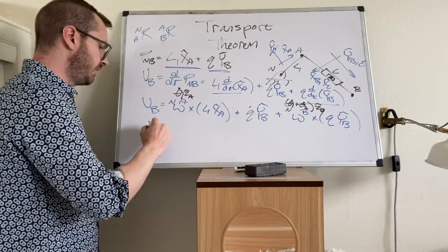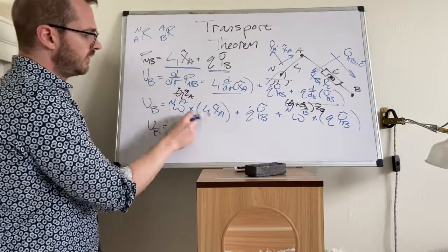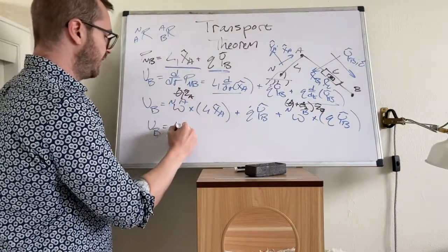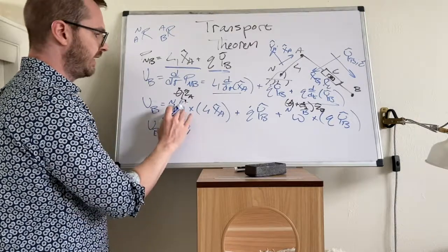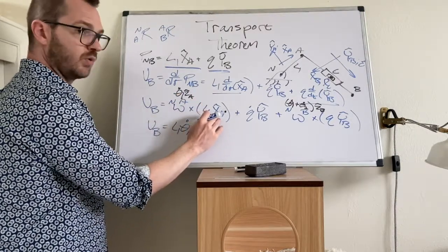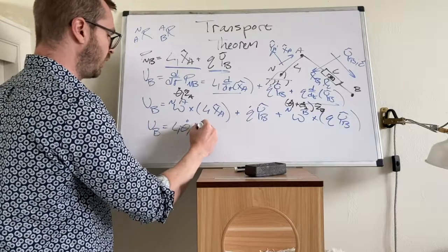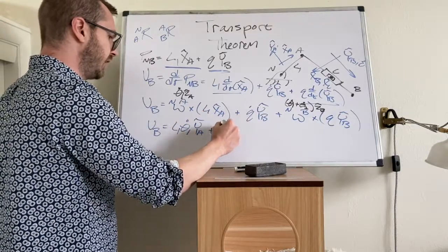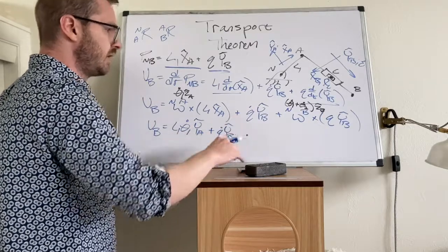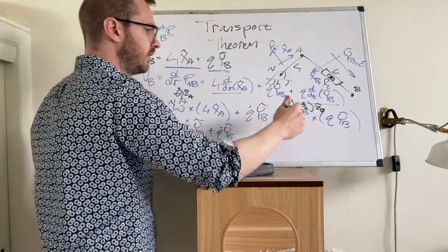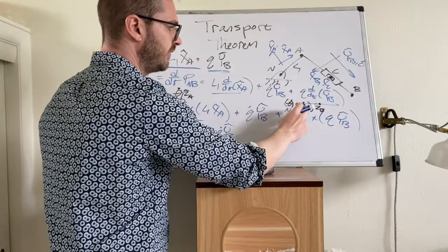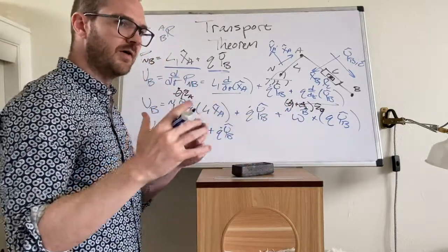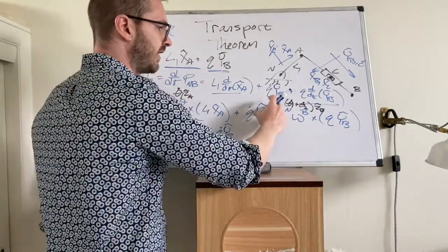Okay, VB. Multiply the scalars together, L1 theta 1 dot, and it's Z cross X, which yields positive Y. Bring down the scalar, Q dot YB. And then next, theta 1 dot plus theta 2 dot. That's a number, whatever it is, these things are going to travel together.